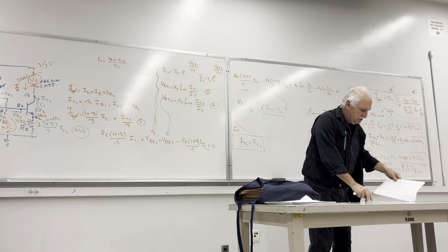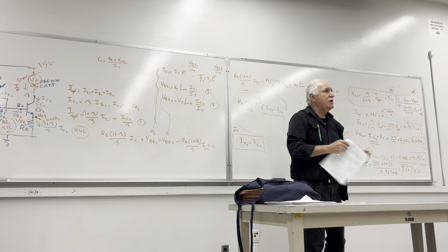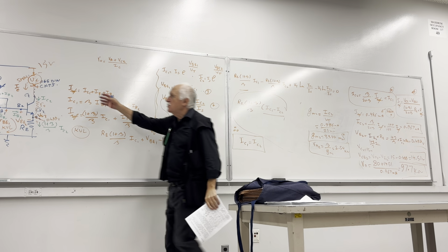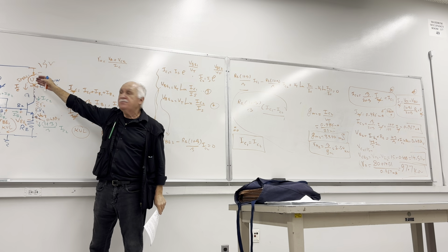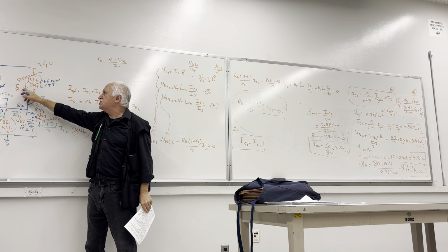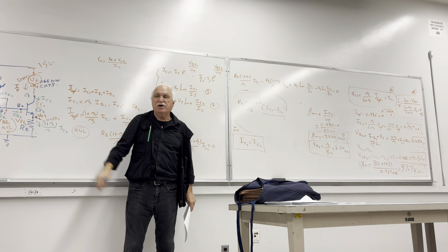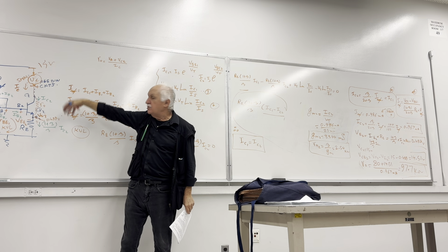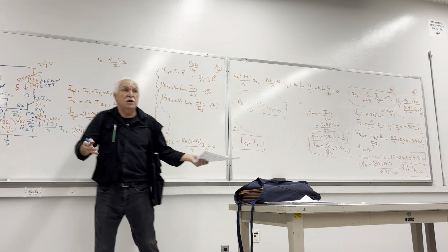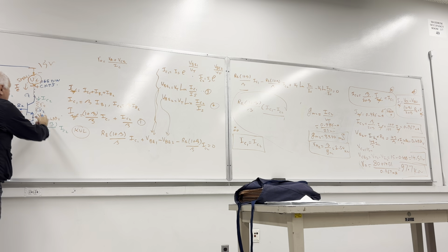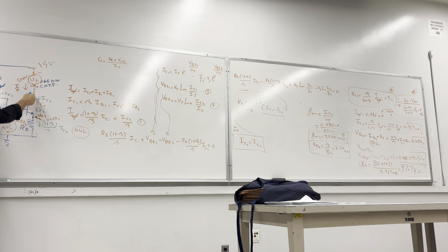And now, the rest. Now we break here, we inject the test signal, and we want to know what is the test current, the small signal test current that flows in there. There's got to be a current, because although it is a constant, it is not constant because of the RO.